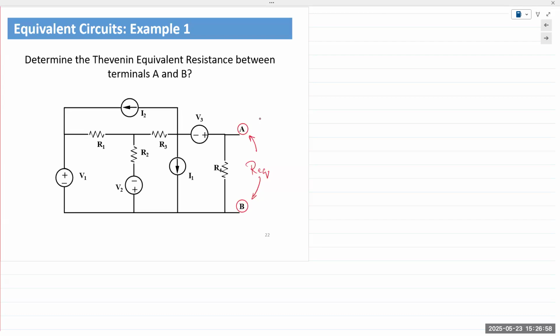anyone remember? What do we do with voltage sources? Well, short, yes, but not shorting the source. We replace it with a short circuit. Yeah. And there are some labs that we teach for non-E majors, and one of the things we would get in the habit of is distinguishing between saying short the source or short the terminals where the source was connected.